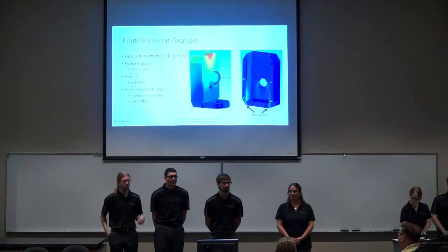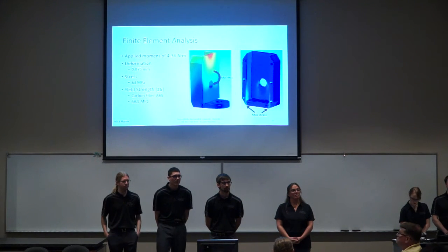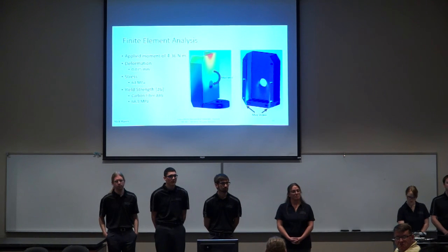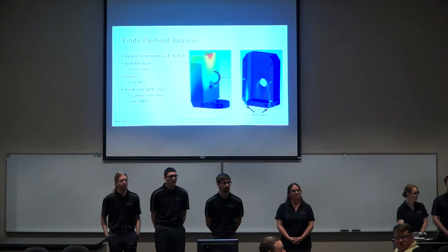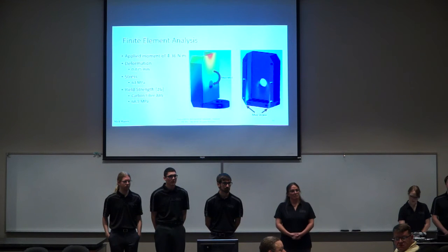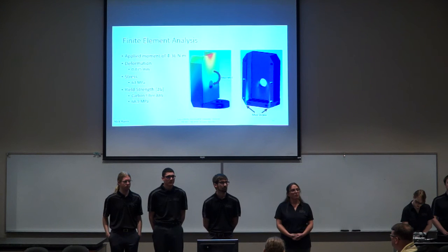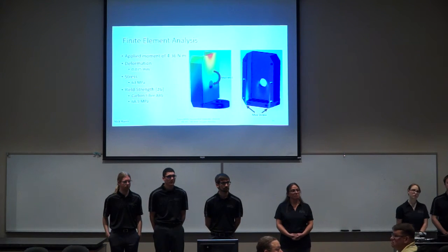you have a deformation of 0.075 millimeters, and you mentioned during the presentation this is acceptable. Based on what? Is there a requirement associated with deformation? On slide 34, how much deformation is acceptable until you start seeing a deviation from the motion that you're expecting? Is there a requirement for that? There has to be. If you're going to make a claim, this is acceptable, this is not acceptable.